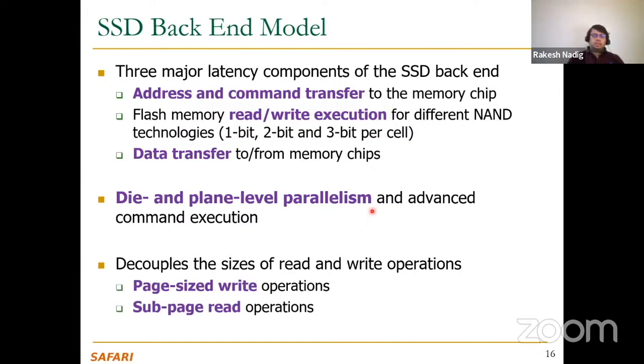So these are some of the latency components, and the simulator also needs to be aware of the size of the read and write operations. Write operations are typically performed in a page-sized manner. So if the SSD supports a page size of around 16 kilobytes, the write operation should always be performed in the page size, but read operations can be performed at a finer granularity.